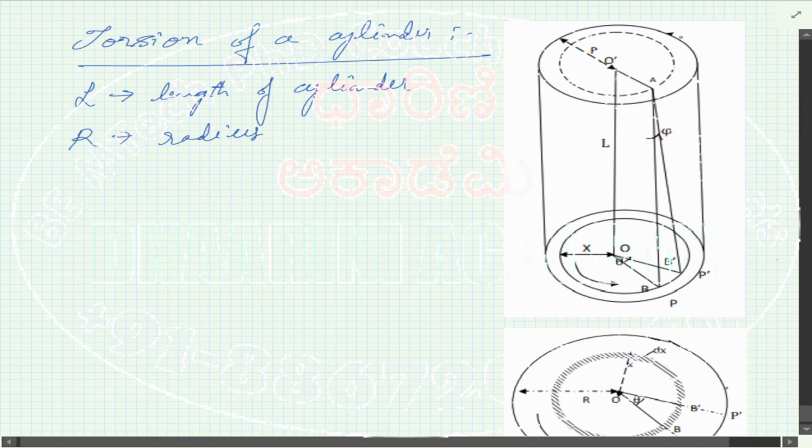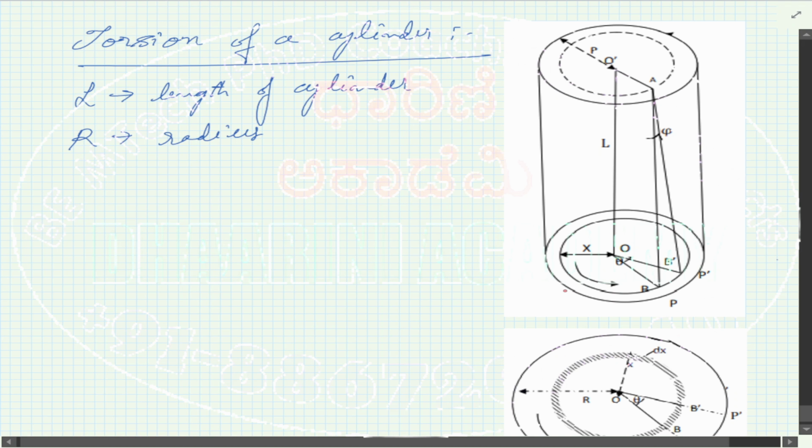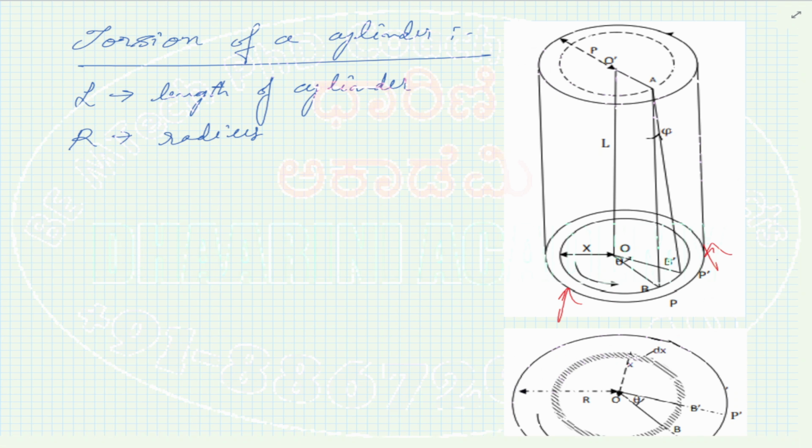You can see here, I'll change the color. So this side is fixed. I'm not able to move. But here you can see that you are actually trying to twist your cylinder in one direction. That's why we call it a twisting couple. So at two sides, because you hold the cylinder at 2 points, one here and one here, and you try to rotate. That means you are applying the force at 2 points. So force that is equal and opposite is called a couple. Already we have seen that maybe in any other force chapter. Correct. So let's try to write this point now.